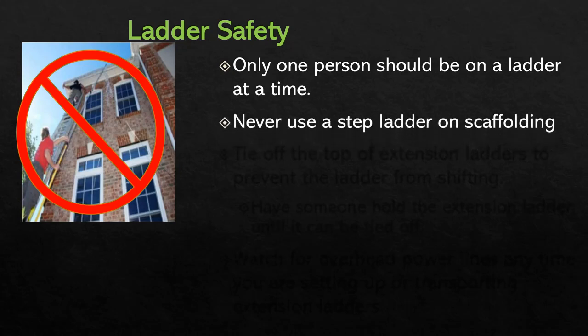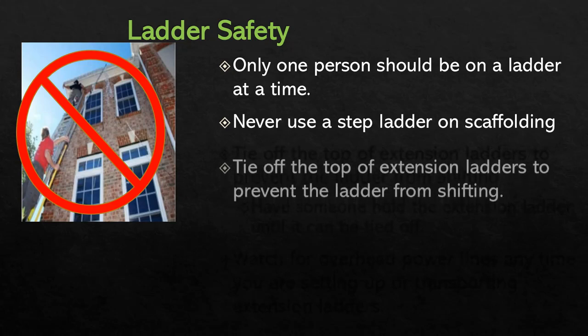Never, ever use a step ladder on scaffolding. That's a combination of too many inherently unstable things together. There are much easier ways to get greater elevation, like building an extra couple of bucks on your scaffolding. But using a step ladder on scaffolding is an inherently dangerous activity.